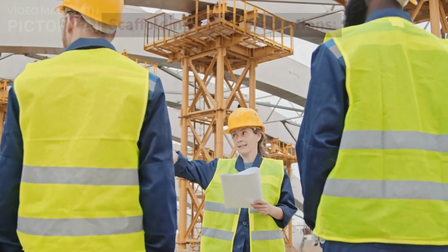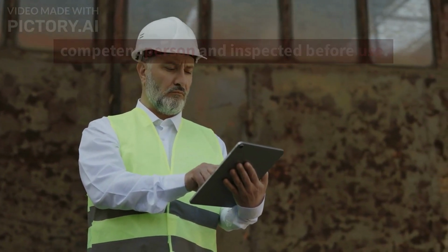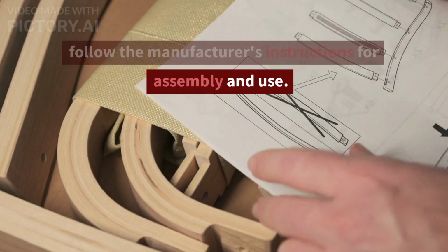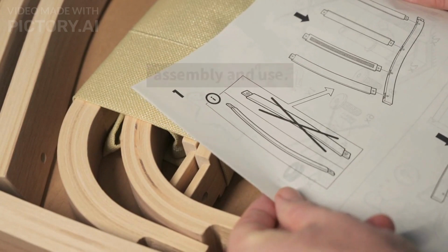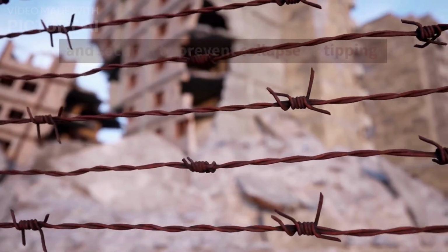Scaffolding safety precautions. Ensure that the scaffold is erected by a competent person and inspected before use. Use proper scaffolding components and follow the manufacturer's instructions for assembly and use. Ensure that the scaffold is properly anchored and secured to prevent collapse or tipping.